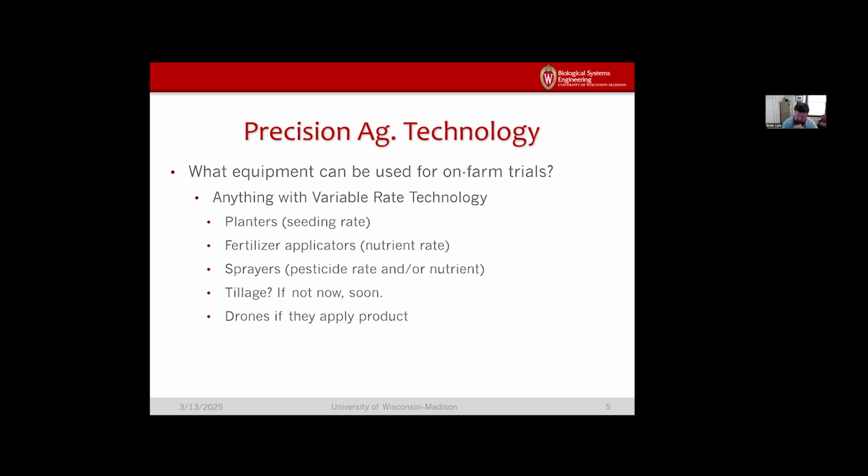Depending on how the sprayer's set up, you can have all the way down to individual nozzle control, which can be as simple as just on off. So I can turn on and turn off nozzles. But if you get into some of the Capstan, Deere has it, all of these See and Spray things, they actually have a potential to actuate the valve via pulse width modulation. I'm not going to go into how all that works, but in the end, basically, we're fluttering the valve.